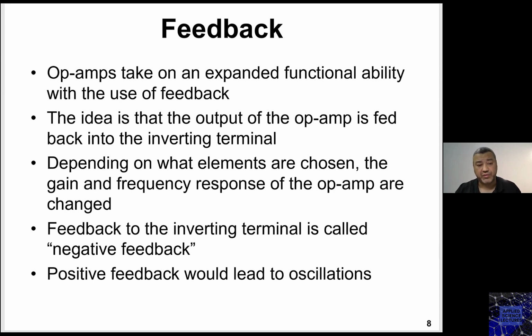The feedback is going to have more control on the gain, bring the gain down, and at the same time increase the frequency response, or the frequency bandwidth of operation, for this op amp. So we always use the negative feedback, and we'll talk about that shortly.